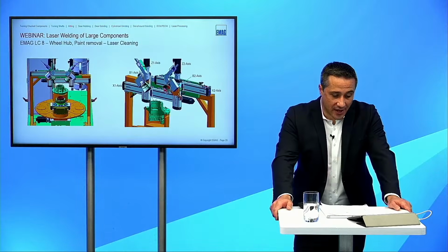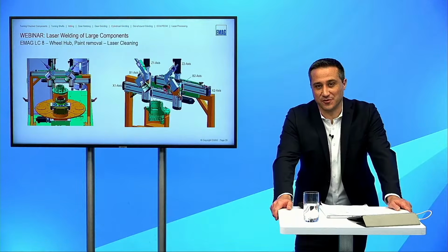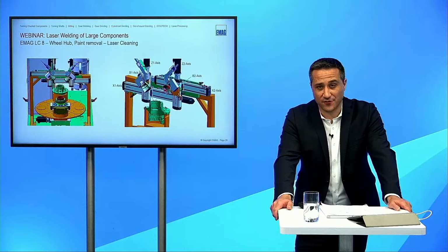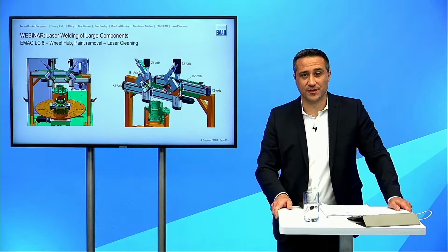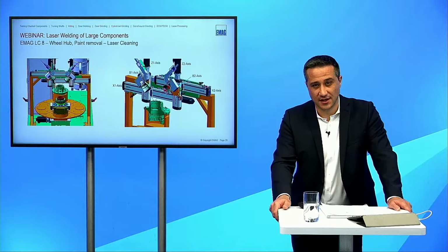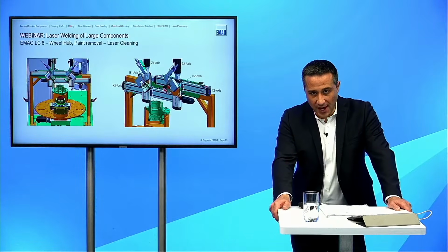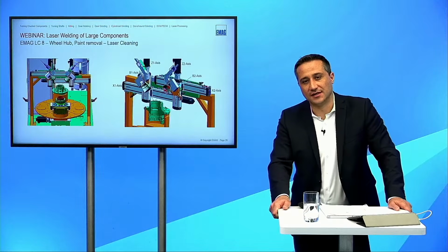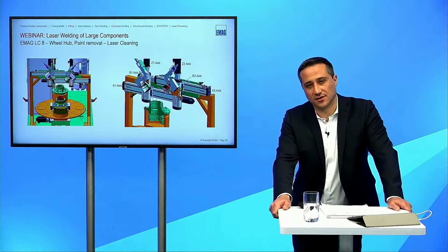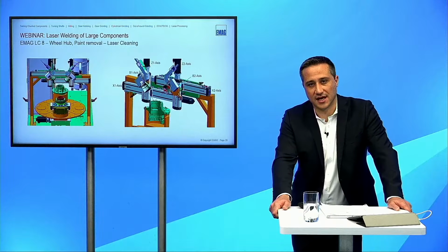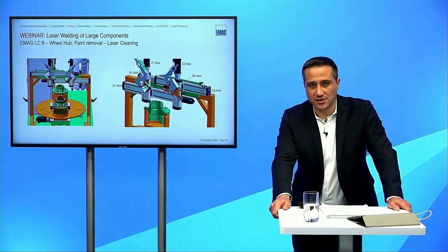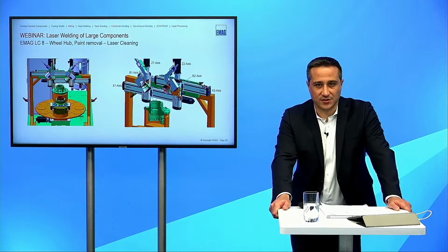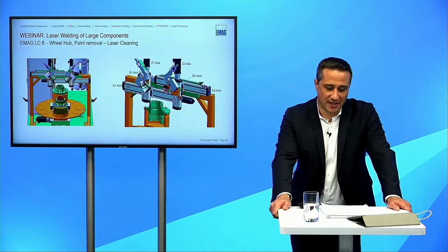How cleanly is the paint removed? At the end, it has to be removed as our customer is requesting it. We first started with these workpieces with a 200 watt pulse laser. We figured out that we are able to realize it, but unfortunately not in the expected cycle time, and therefore we decided to increase the laser power itself. So we implemented a higher power pulse laser source, and we ended up at 300 watt, and that was the way to achieve the expected quality.